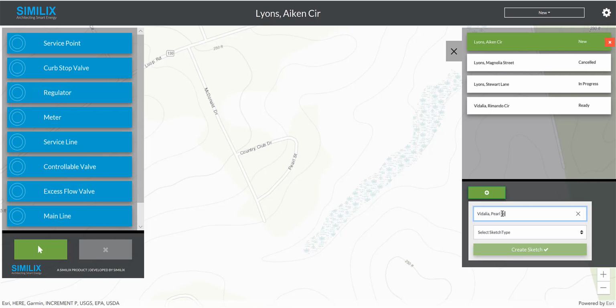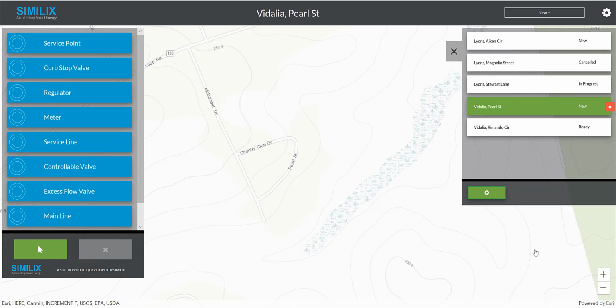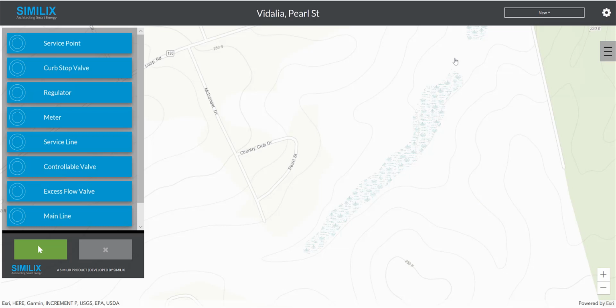Now, in the sketch tool, I have pre-configured a number of sketch types, where a sketch type is actually a kind of template for different types of sketches I can do. So what I'm doing here is I select the sketch type that should be the foundation for the sketch I'm about to make. You can see I have the possibilities: simple extension, standard extension, and special extension. I go with the standard extension and I click here, create the sketch. Now I have my empty sketch.